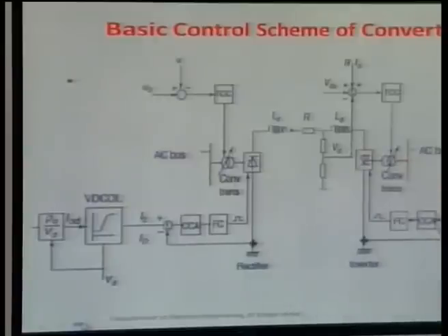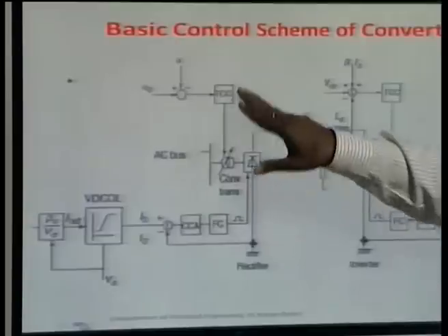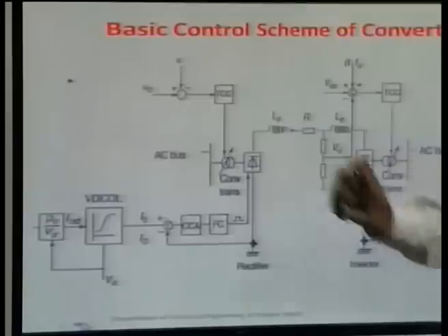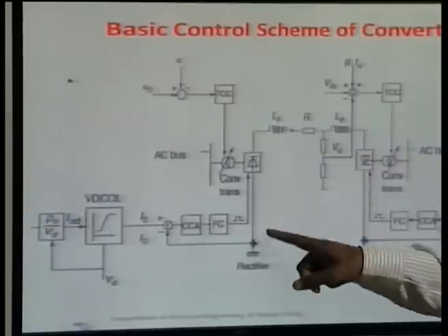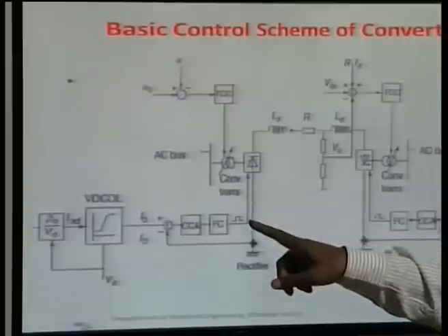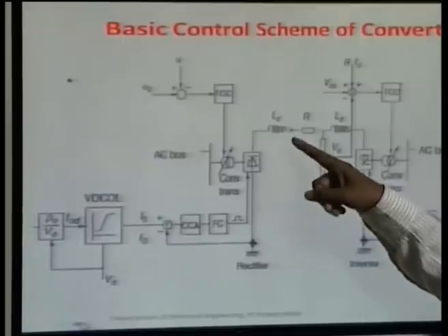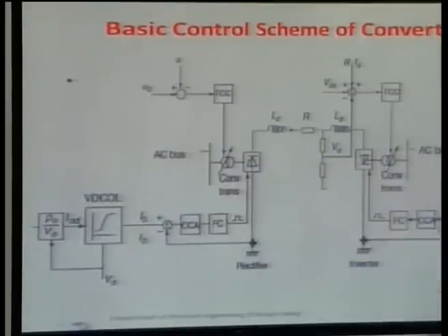If there is some mismatch, the tap changer will start, and it will try to change your converter station, the rectifier, and the tap will be changed to control the current again, because this alpha is decided by current, and this also changes the voltage. So there is a complete impact here.